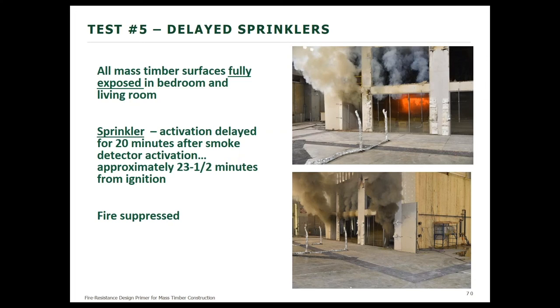the fire was suppressed. We were not sure what would happen with the delayed sprinkler activation. In essence, what happened was the piping got so hot that when the water was turned on, it immediately turned to steam, and the steam displaced all the air in the room, quickly putting out the fire that was nearly at flashover at that 23.5 minute point.